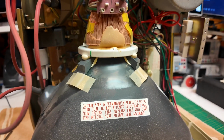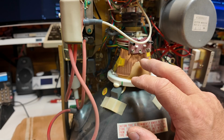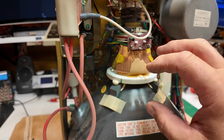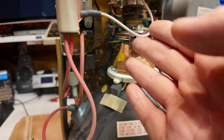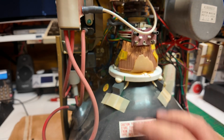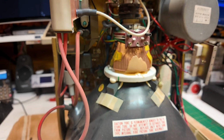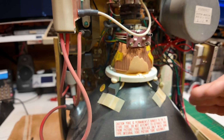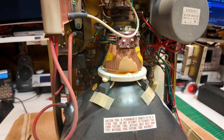And then of course you have your anode voltage that feeds down on your anode cap here. And yeah, that's it. So basically there's a circuit that feeds two circuits inside of this, which is the deflection yoke. This is just a big electromagnet, and it'll be fed voltage that will cause the stream of electrons heading towards the front of the tube to either swing this way or this way, and then there's another field that will be created that allows them to swing up and down. So the voltage that is supposed to be feeding this to allow this to swing up and down is the voltage that we're missing, and that is what we've got to figure out today.